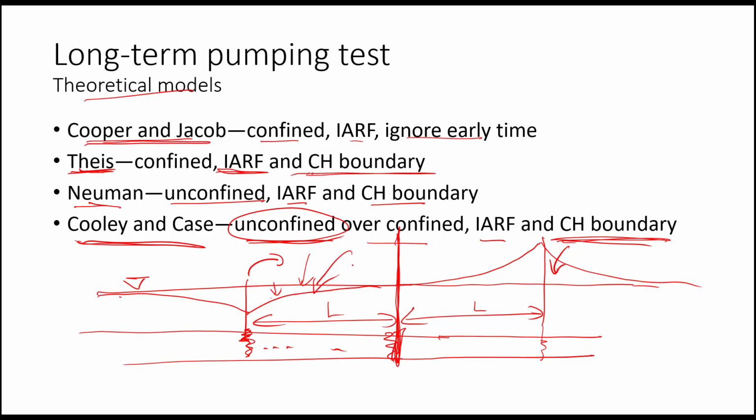So it's going to be the same as the heads here, except they'll be positive instead of negative. And what happens is, as I continue pumping on this well, the solution for the infinite case, if I have an image well, is going to look like this, the heads for the image well. And if I add these two together, here this is 0,